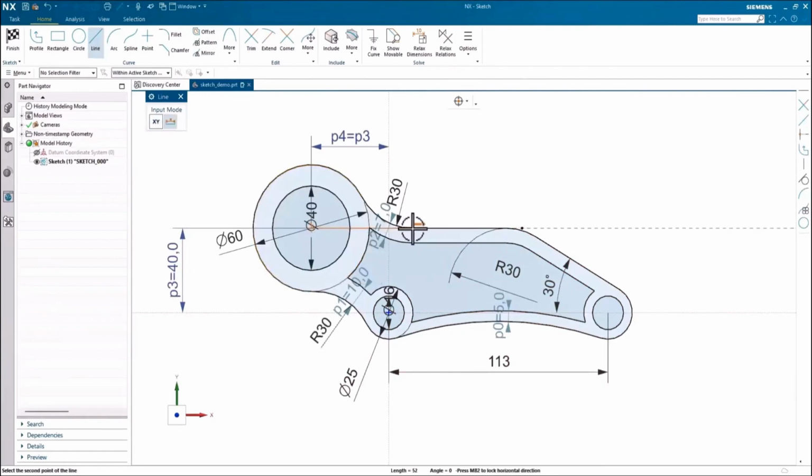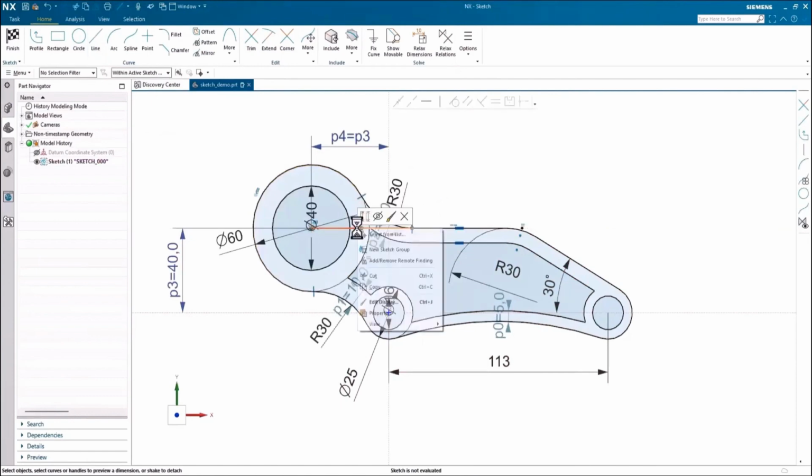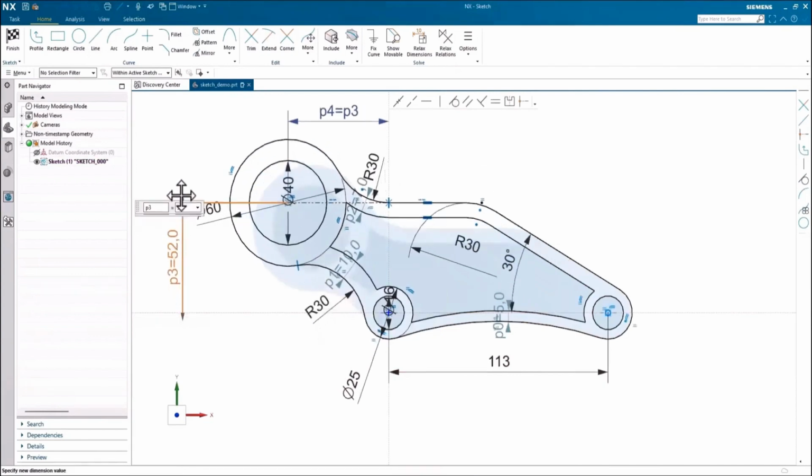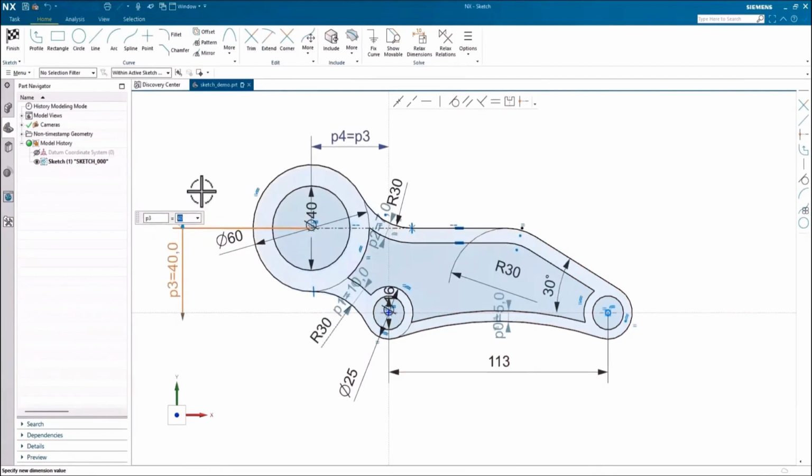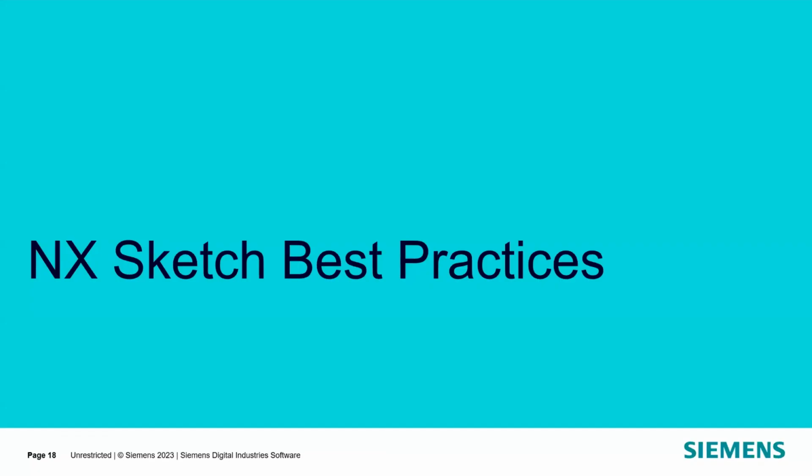If you take any of the dimensions off, here you can have reference geometry. So similar to before, maybe you want those to be collinear across there, but you can convert that to reference geometry. Or if it's something you want to have it tangent to, you can do those as well. So see here, as we adjust that height, the rest of the sketch is moving along with it. So just some ways to quickly go through and show a little bit more detailed example of how that goes. So that's the fundamentals with that.